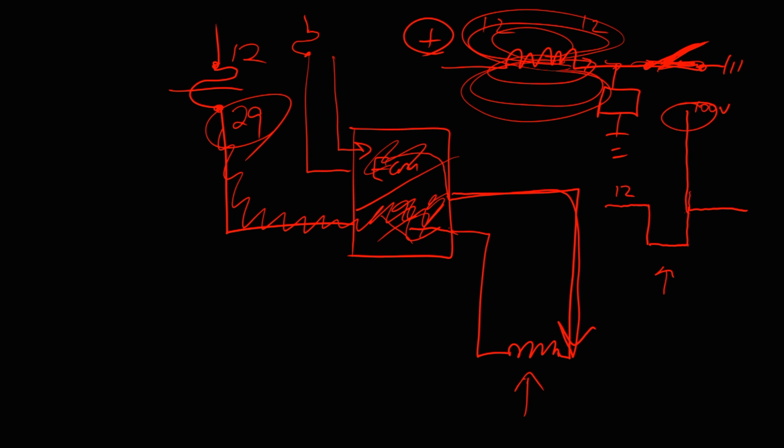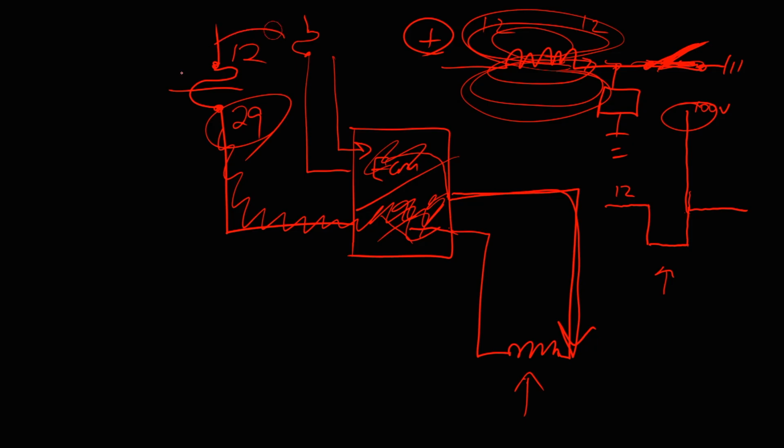Fuse was blown. That's it. Plug the fuse in, vroom. That car got an engine computer, that car got a wiring harness, that car got thousands of dollars of components. It wasn't blown. I'm sorry, it was a fuse that was relocated in the wrong spot. So it was an empty fuse. So these numbers are right, 12 and 29, but there was a missing fuse there. The engine fuse was put in the wrong location below it.